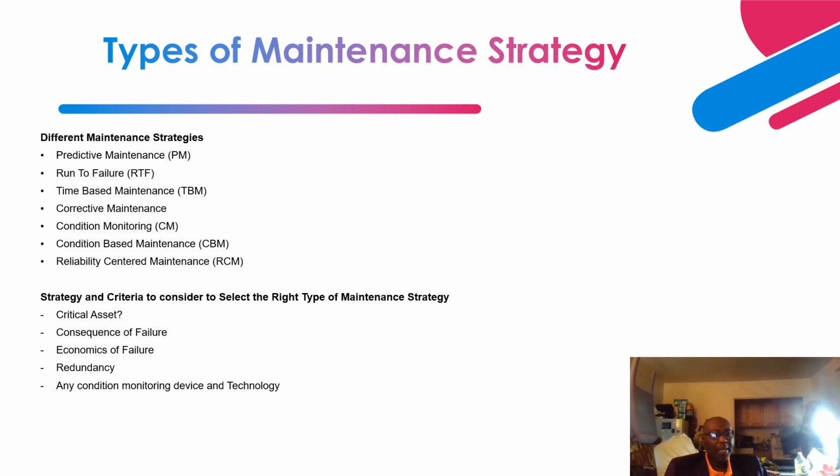Based on the criteria I've mentioned, that is the criticality of that equipment and the safety part, let's say if that equipment should fail, what is the consequence of it, the safety hazard it is going to create, and also the critical customers that equipment is feeding. All these criticalities have to be identified and reviewed for you to successfully implement a reliability-centered maintenance strategy.